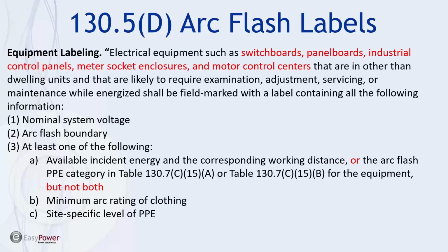And this, in my opinion, was offered to the companies that had already described hazard risk categories and were utilizing that nomenclature, so they wouldn't have to rewrite all their manuals, but could just define what their categories would be and use that as the alternative to referring to HRC. So again, we can't refer to HRC when we're talking about levels of PPE.